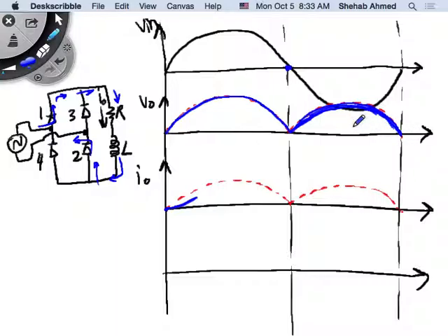So how does this change the current? Now my RL circuit has a positive voltage put on it again. How does your voltage go to zero? Wouldn't it not ever touch zero? No, it will touch zero. With an inductor, current may not touch zero, but voltage will, because it's the voltage of the input source, and the supply voltage is crossing zero. And it's because it's trying to cross zero that diodes 3 and 4 started to pick up.